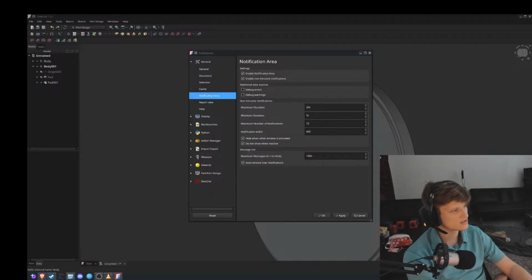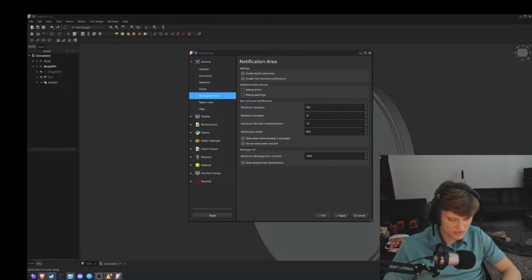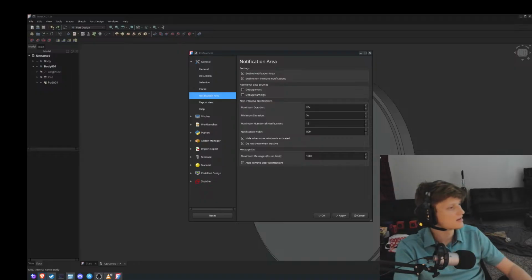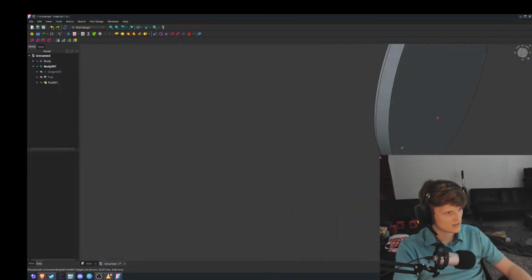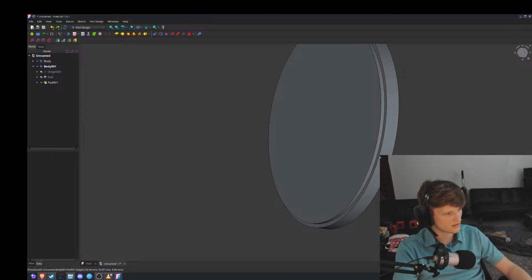FreeCAD allows you to change the themes to Blender mode. Because if it can teach me how to do it with Blender mode, it'll teach me how to do the other modes, right? Blender mode navigation. You can change the setting in the drop-down menu located at the bottom right of the interface next to the coordinates readout. Wait, what? That's weird. Oh, here we are. Hello, Blender. Yes. Okay.